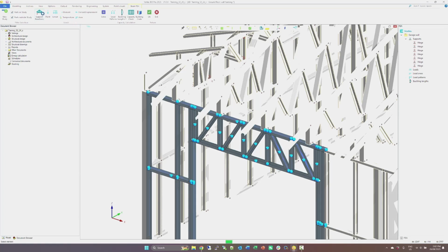To be able to use this function, we need to have truss engineering done for the trusses because the reaction loads are from the truss engineering results. The load transfer must be unfactored and it will be resultant of multiple different load cases. Therefore, we are importing multiple reaction loads into the current study. It's going to take some time, between 3 to 5 minutes.